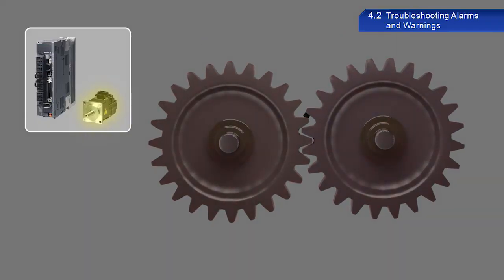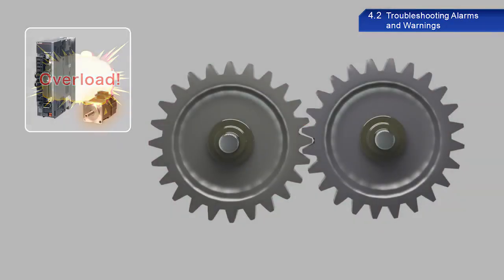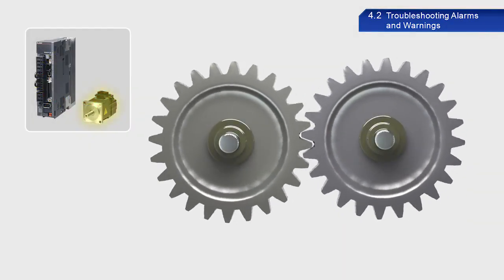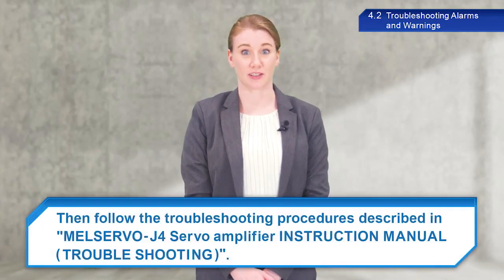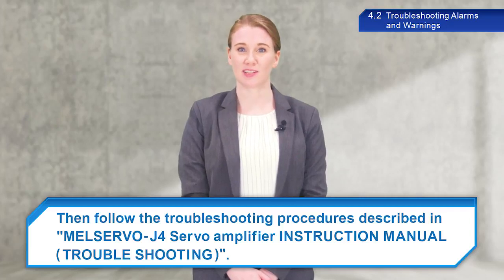Excessive current may then be output to try and move the part normally, which causes excessive load and triggers this alarm. If this happens, check mechanical parts carefully. If this alarm occurs when there are no mechanical issues, wiring may be disconnected or connected incorrectly, so check the wiring. There are many other alarms that could occur. Follow procedures in manuals when other alarms not covered here occur.